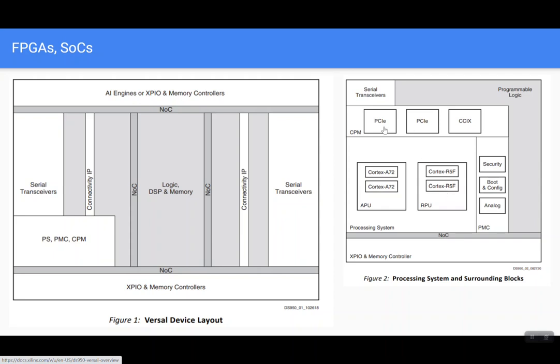And it has PCIe kind of buses which you can utilize, the serial transceivers. And we will learn as we go, memory controllers and this and that. We'll learn more as we progress in this particular course. An important thing here, as you can see, there's a security unit as well. In all the popular microcontrollers, microprocessors, DSPs or FPGAs, you will find security blocks or security features to make sure that your firmware, your design, is properly secured.